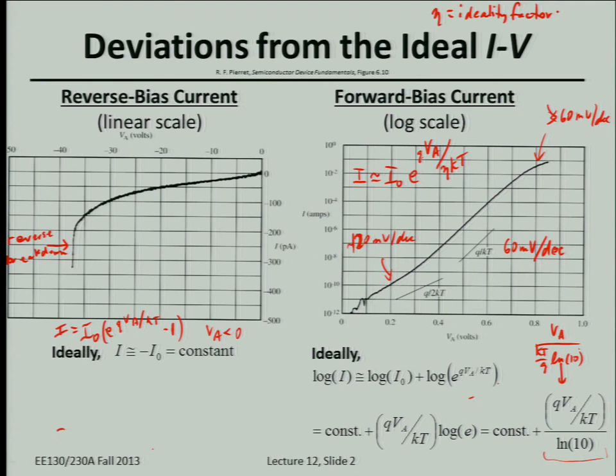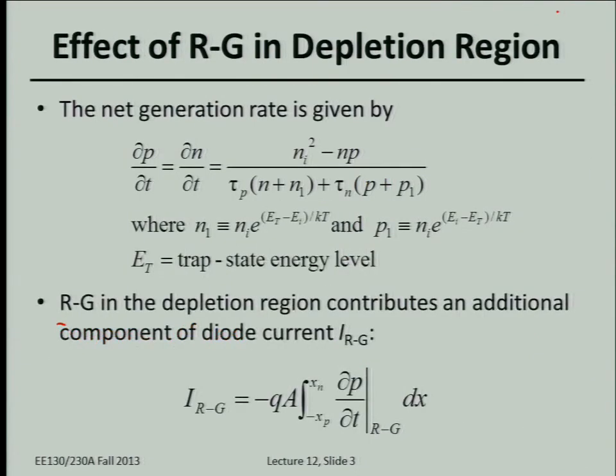Okay, so today's lecture is just these three points. What is the source of those 3 non-ideal behaviors? So let's just look overall. For a couple of those behaviors, it turns out that our approximation that nothing is happening in the depletion region, that carriers are just flowing through, is actually not a very accurate assumption. So in reality, we have either recombination or generation. Okay, so we know there's various kinds of carrier action, right? There's drift and there's diffusion, but generation and recombination can affect current as well through the carrier concentrations.